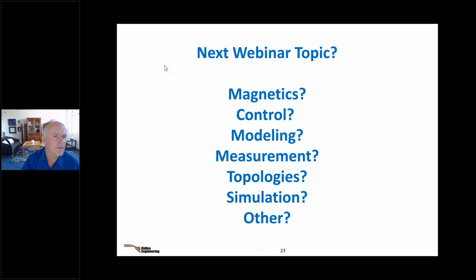LLC for ultrasonic driver. Well, Charles Jenkins asked the question, can I use LLC for ultrasonic driver? Well, that was my very first project. No output rectification. We were running at 20 kilohertz. We used an LLC. It didn't blow up very often on the switches, so sure, try an LLC for an ultrasonic driver. Is it the right answer? I don't know. I'd have to know more about the specs for that. So there you go. I've got everybody's questions. Thank you for the feedback on the next topology.